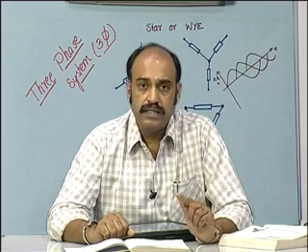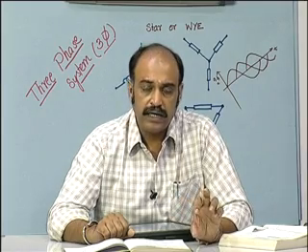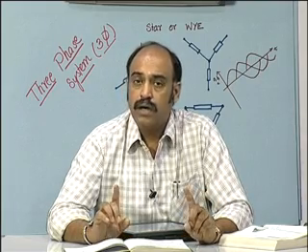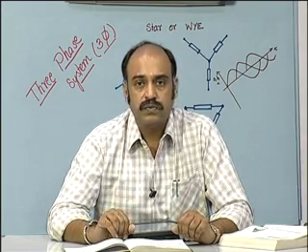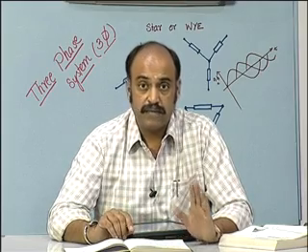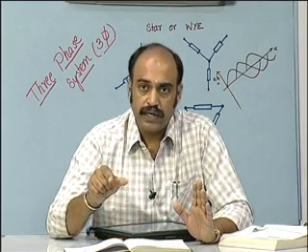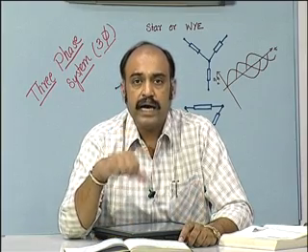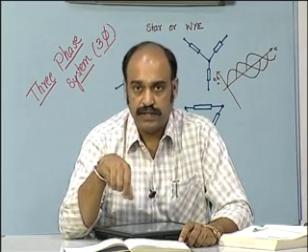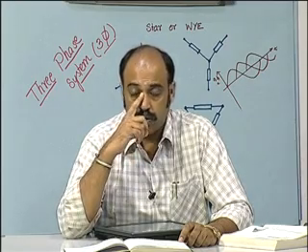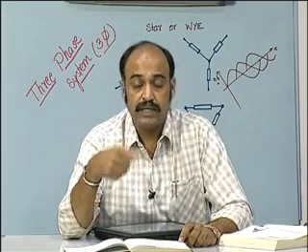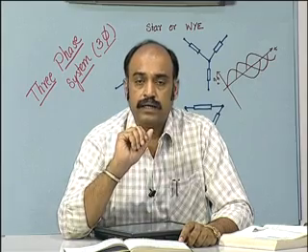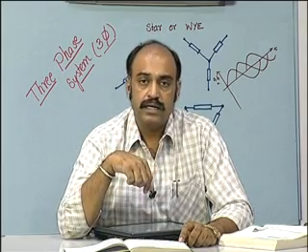In order to balance the line currents, that is, the line currents should have the same amplitude, effective values, 120 degrees displaced from each other in the spatial coordinate system, we do a modification in the delta circuit by including two reactive loads in the other two phases. So, we have a resistive load which is the active power which is going to be drawn from the mains. It is still going to be only the active power which is drawn from the mains, but we add a capacitance and an inductance in the other two phases